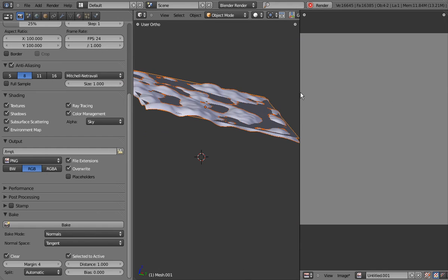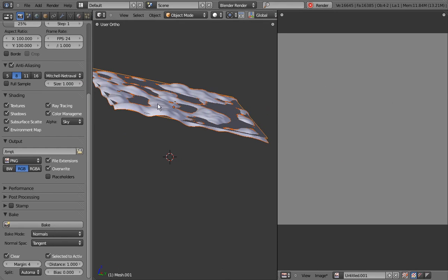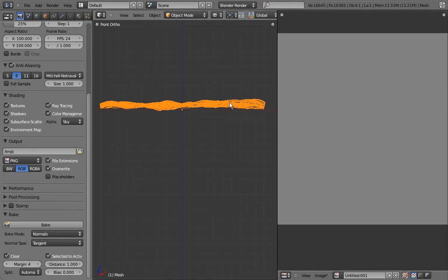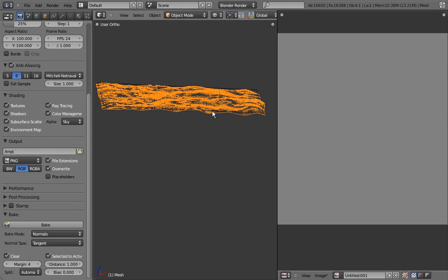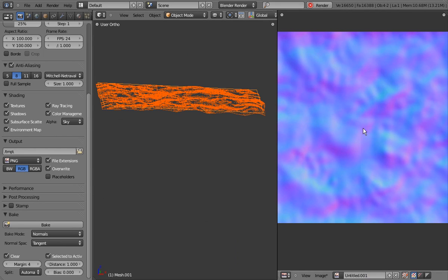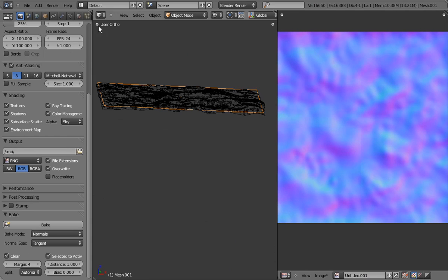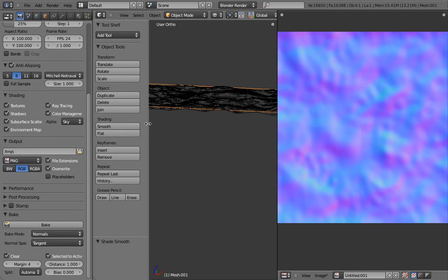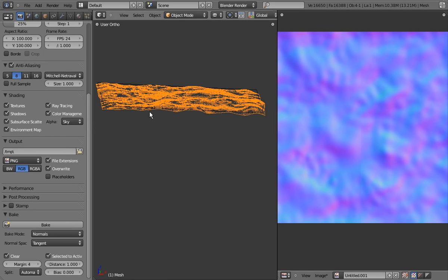So here I was just double checking if that was indeed the problem, that it wasn't subdivided. It was, so I subdivided again. I bake it again, but I end up with seams again, because I didn't set smooth it yet. So there I went into the side panel, pressed set smooth on the low poly plane, baked it again, and we're finished.